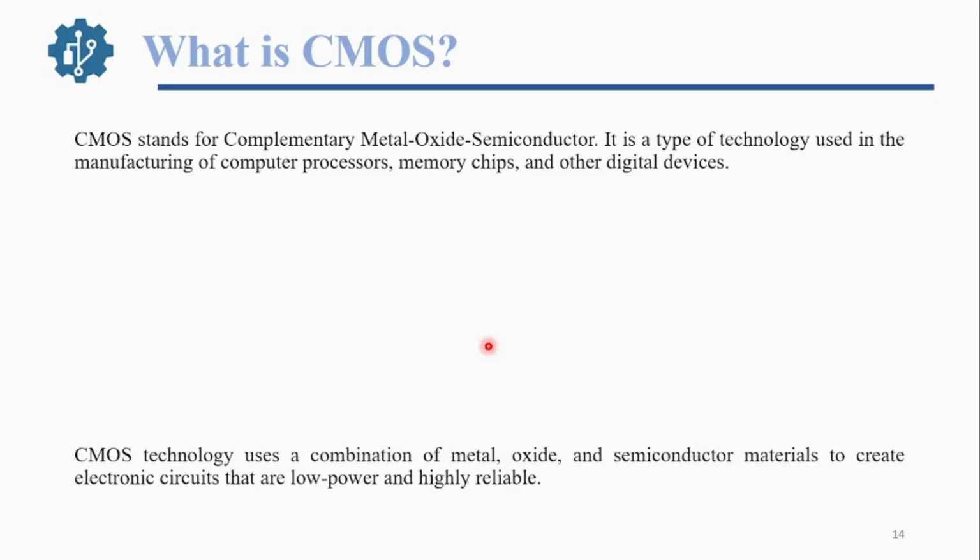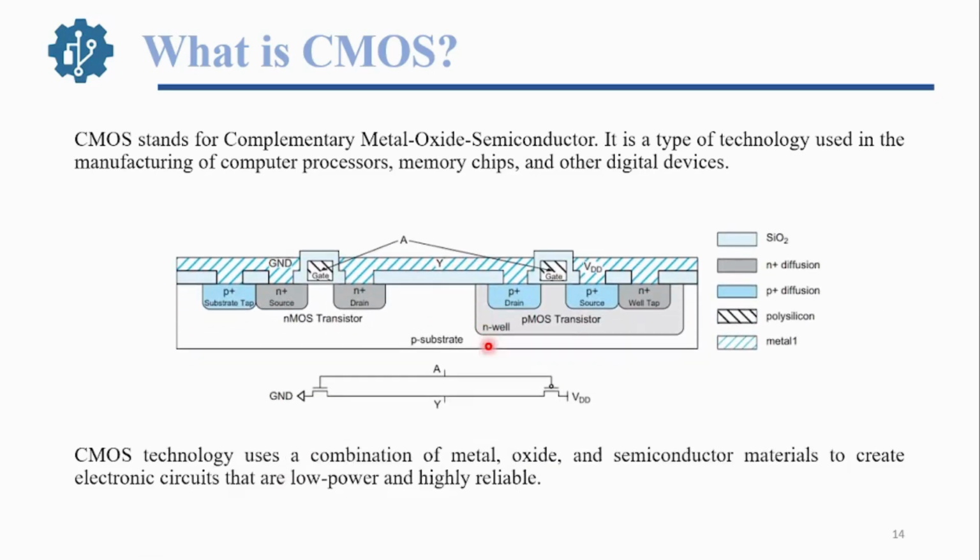Basically, all the electronic circuitry, like making a simple op-amp, creating a mux, clipper and clamper circuits, gates, and all types of combination of applications are based on the CMOS technology. And this is the complete 2D structure and 2D overview of the CMOS transistor. The CMOS technology is a combination of the two transistors, NMOS and PMOS, shown here.